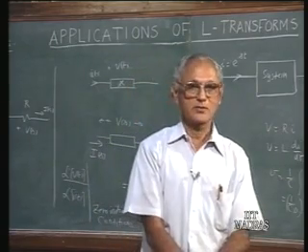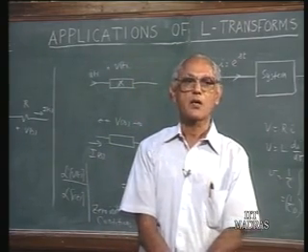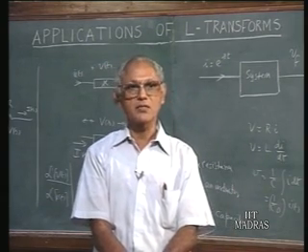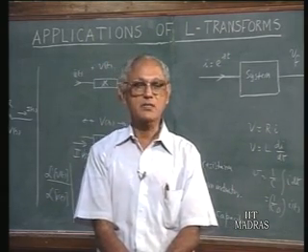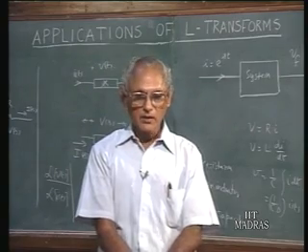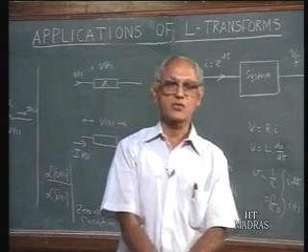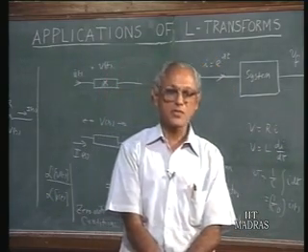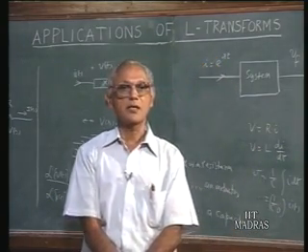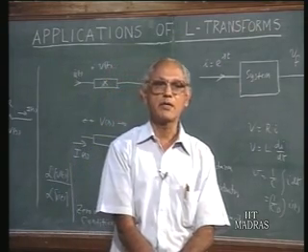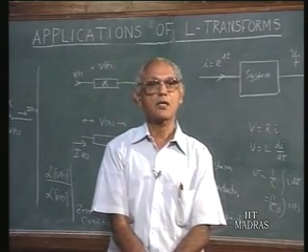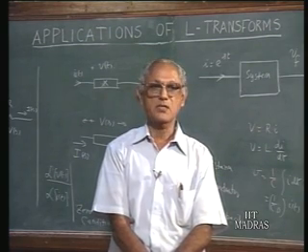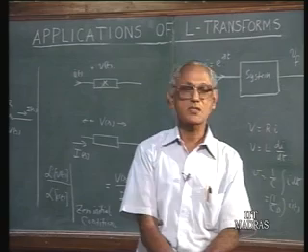A third point which is new here is whenever the inductors carry initial currents and whenever the capacitors carry initial charges or initial voltages equivalently, then we represent those initial conditions by equivalent sources in the transform diagram. So we can have a voltage source representing the initial current in an inductor, or a current source. Similarly, we can have a voltage source representing the capacitor voltage or a current source equivalently. So the only difference is that we have initial currents represented by additional sources, excitation sources.